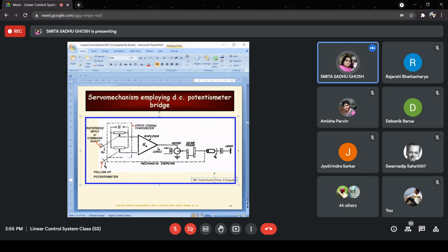It's going to be either in degrees or in radians, theta r. Now this element is connected to it and is acting as a feedback. More about that in a moment. If we look at the output of this element, we find that it is going to be a voltage which has been generated and is proportional to theta r minus theta c. That voltage is being applied at the input of this amplifier, an op amp maybe.